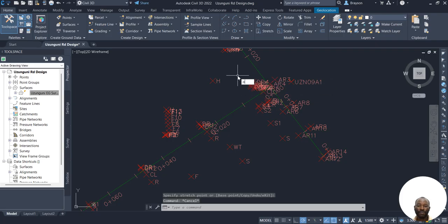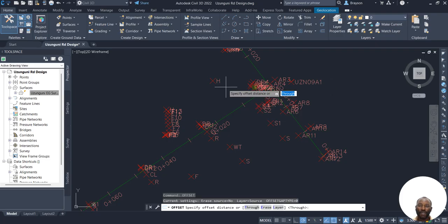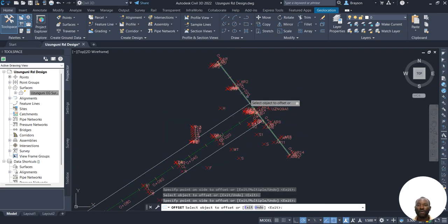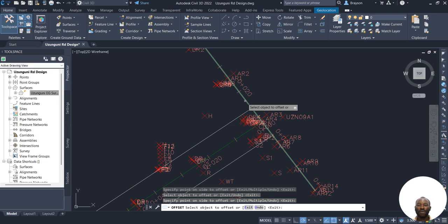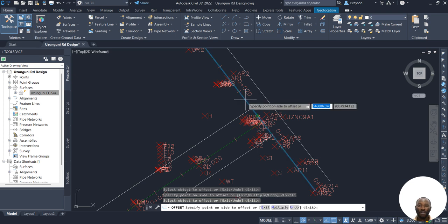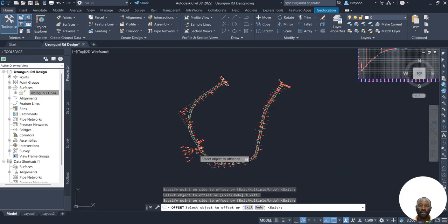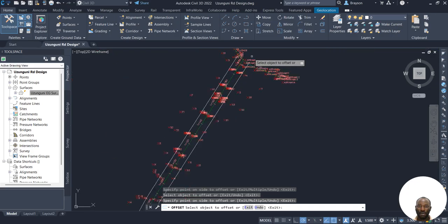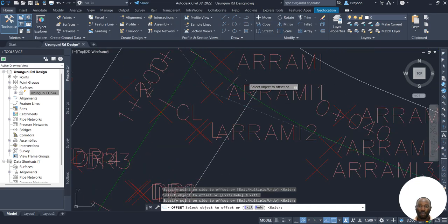How do we offset it? I take the offset command, and my offset distance is 5.45. I'll do it for both axes, although it is not necessary for the axis to be the same as the main body, but for the matter of learning, we can do it.